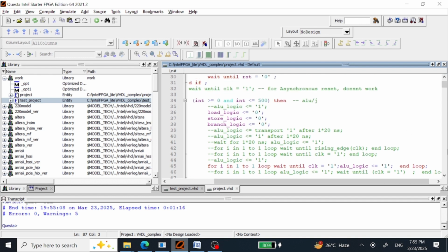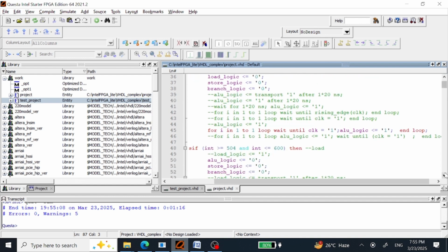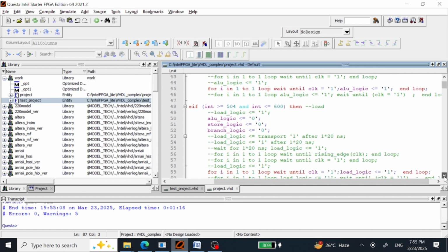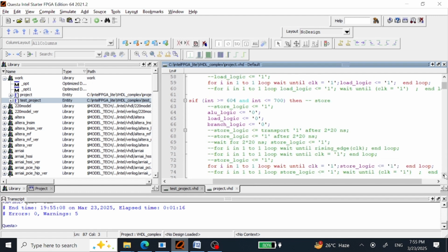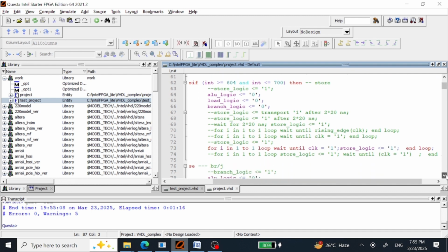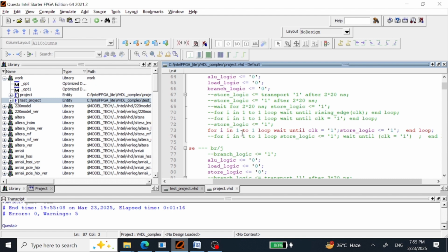Now let's start from the top and go, and we see that this loop we are running from 1 to 1, only one cycle, right? And then this loop also we are running 1 to 1, but we were going to get 2 cycles for the second load one, because one loop has already been done. So this is the way the delays work, like in the case of SystemVerilog, they work more properly. And you see here I was again giving this 1 cycle delay, but in the waveform we saw the signal was getting delayed for 3 clock cycles, right?